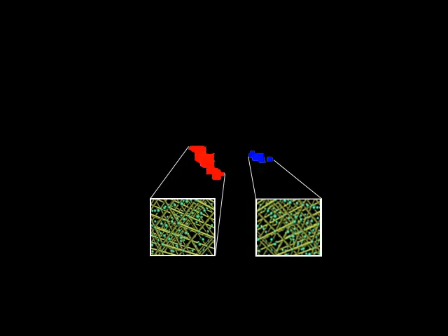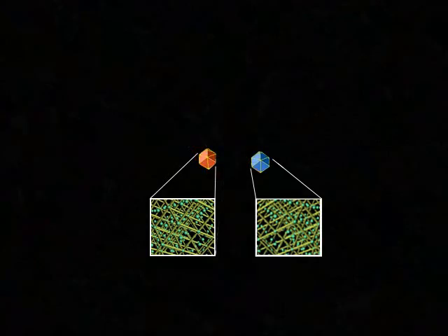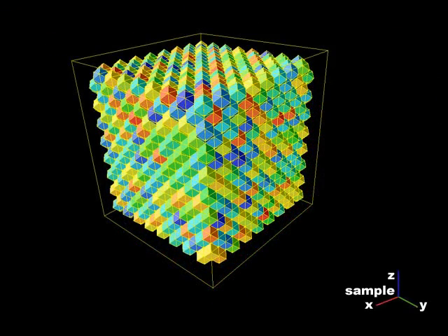In the finite element simulations, we retain the lattice orientation, but approximate the grain shape as dodecahedra. The volume of metal examined in every simulation is thus represented as a cube of dodecahedra, each representing a grain of metal. Again, the color of each dodecahedron displays the lattice orientation of that grain.